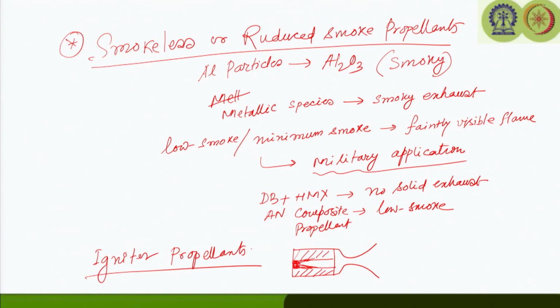For example, for the igniter, we need very fast, high heat release or high gas evolution, so that it can actually give the hot plume to the propellant surface and ignite it. Of course, it needs to have stable initiation of the ignition. It can operate over the required ambient temperature range. Of course, it needs to have good aging characteristics, as is required for the general propellant